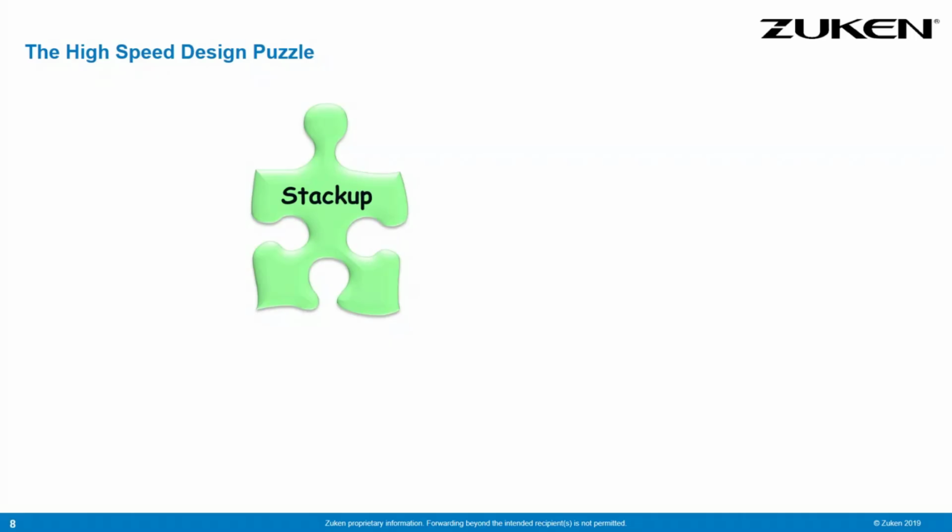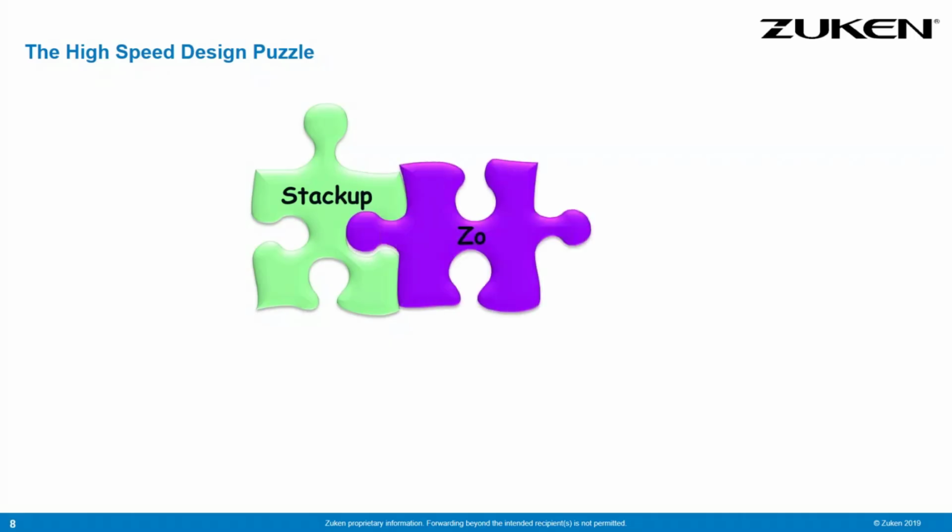If you mess up with the stack-up, curing issues later on by fancy measurements, by squeezing the design to the limits, by adjusting trace widths or dielectric heights, may end up in a complete nightmare. So stack-up design is the most important puzzle piece of high-speed design. Stack-up design goes hand in hand with characteristic impedance. The stack-up will define the impedance conditions of your traces.